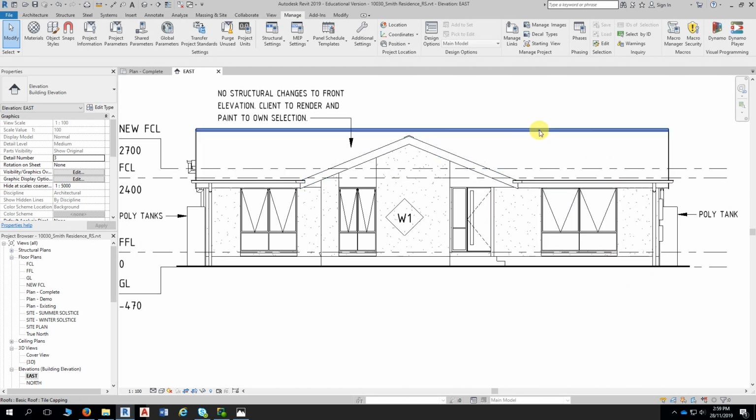And I guess the thing is that they're all the same line thickness because in elevations, for instance, the line work is said to be in elevation, which means that all lines are the same thickness. There's no variation, so nothing is cut. But we can enhance the elevations by thickening up the outlines. And the outlines of the elevations are known as silhouettes.